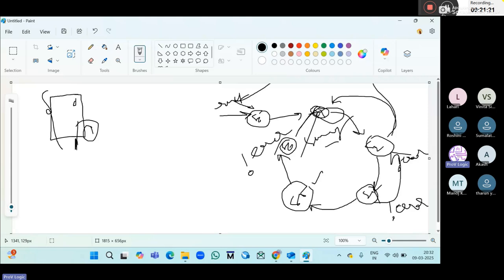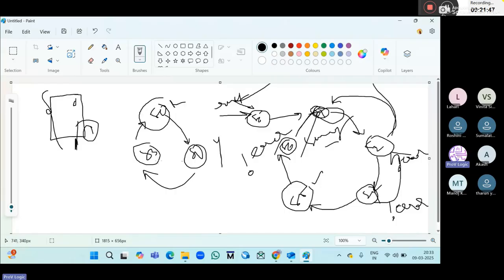Okay. So this entire process we divided into a number of states. Even the traffic light controller is the same. First a reset state will be there, S0. From S0, S1: which light should glow, red or green? Next, S3. Mostly if you go to a simple design, here red will glow, here yellow will glow, here green will glow. We will write what is the present state and what is the next state.